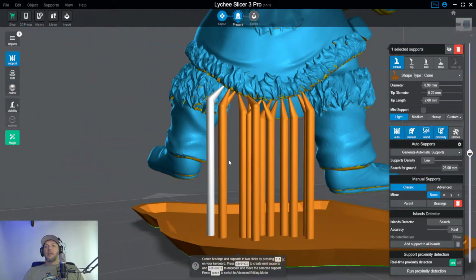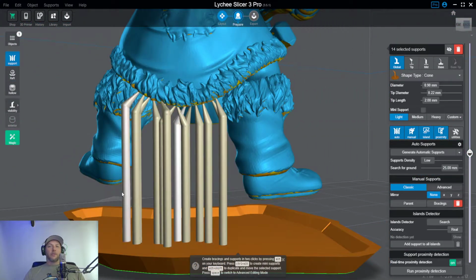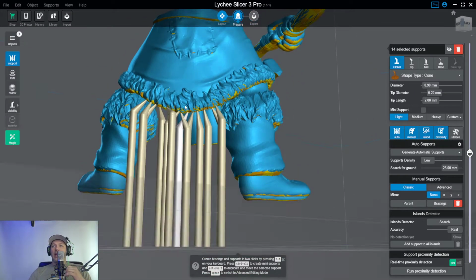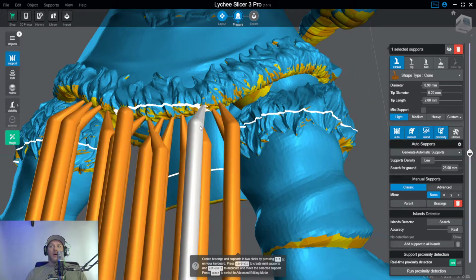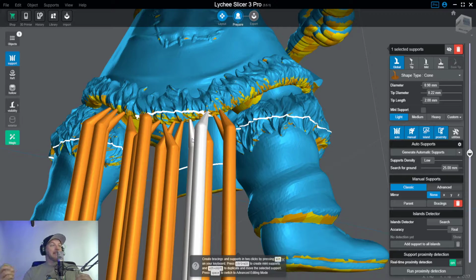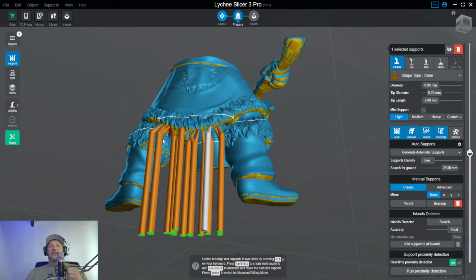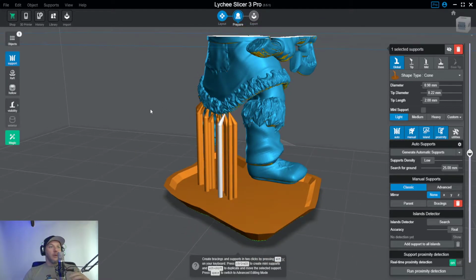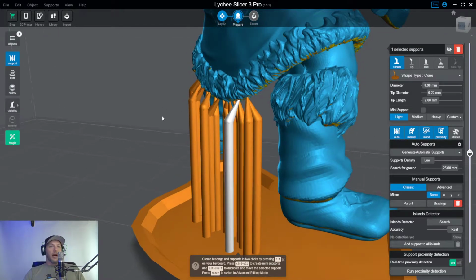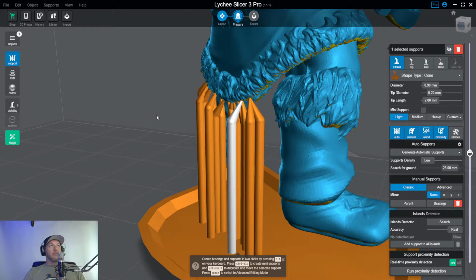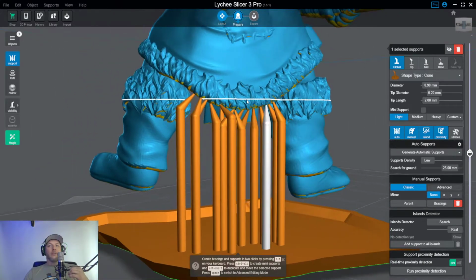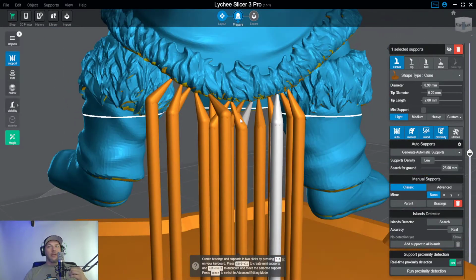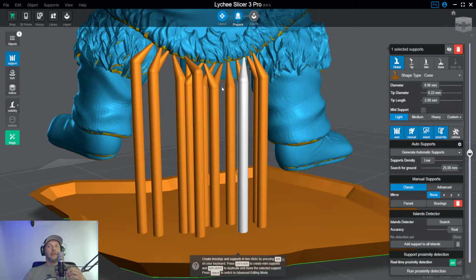So what I've done is I've created a bunch of full-sized pillars, and they do adhere to priority number 1. I am using these pillars to maintain the quality of the model. We're trying to keep that detail. They are easy to remove. You could easily pull these pillars right off the model with no issues. It's not going to trap any spots. It's not going to damage the model. But I don't necessarily adhere to priority 3, which is efficiency of materials, right?